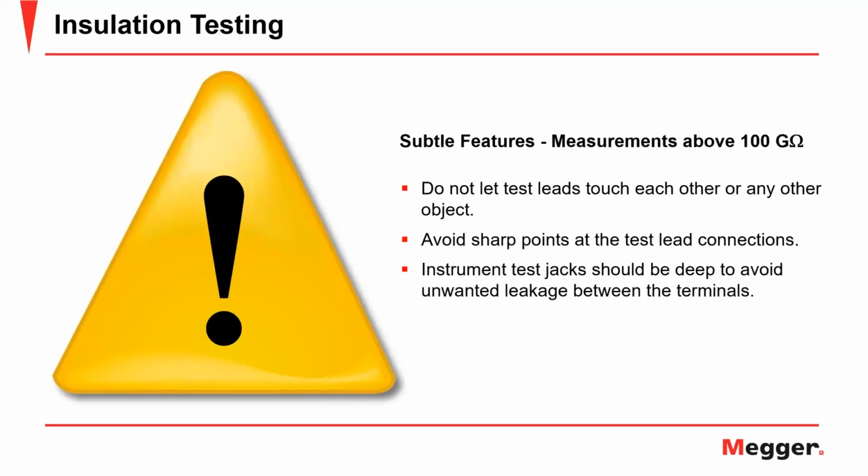And we just indicate, especially on high range measurements, you want to take some precautions. Sometimes you want to, for instance, suspend your leads in air instead of having them lie on a surface, because you can get tracking. So that's just some points on the effective use of your lead set. Next.